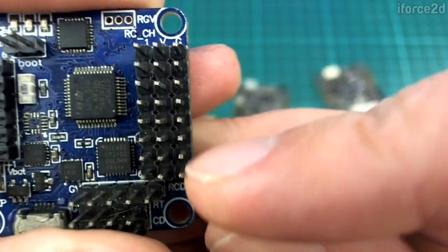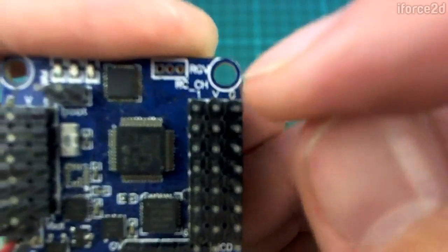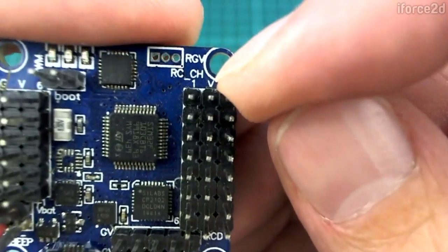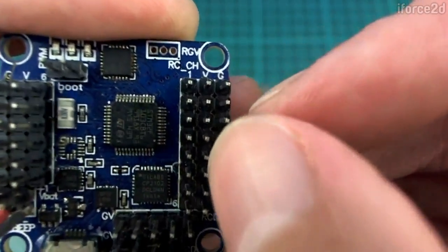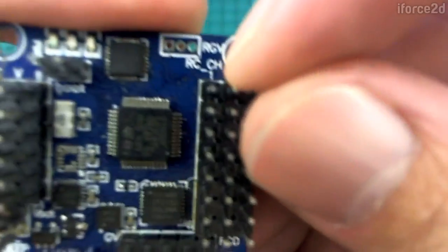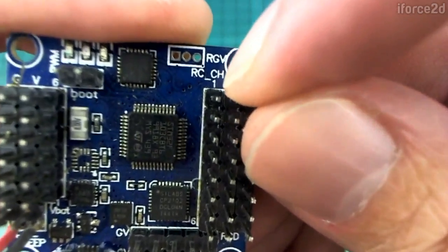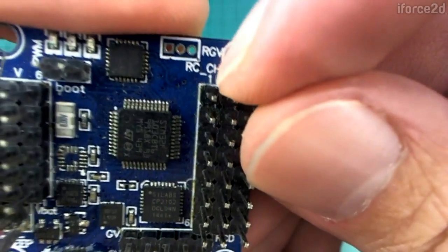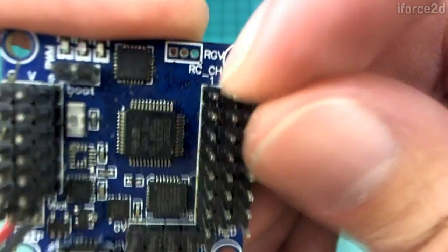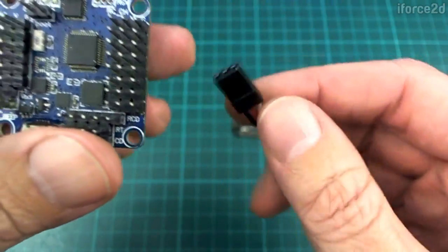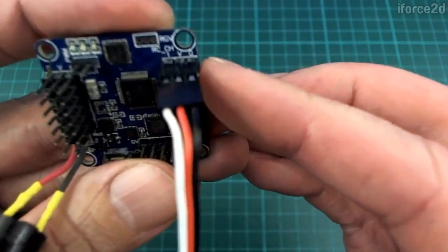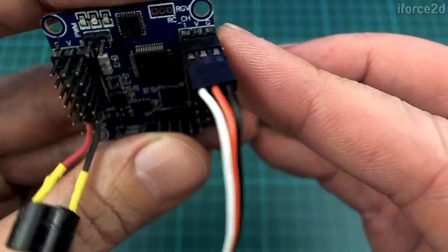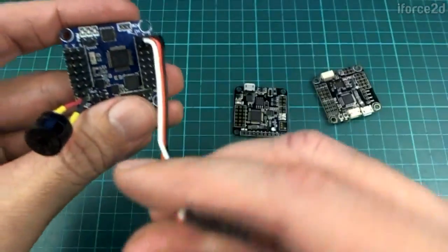And all of these pins down here are all connected to each other, as we saw with the receiver. The middle row is V, so that's volts or power, and 5 volts in this case. And again, all of these pins in that row are connected to each other as well. The innermost row is where the pins are not connected to each other. These are the actual signal pins. And this one's labeled 1, so this is receiver channel 1. And to connect that to your receiver, you would use one of these servo cables, and you would plug it in there. So you've got black, so it would be like that. Typically we would color them black, red, white, or black, red, yellow or something, and then the other end would go into your receiver.